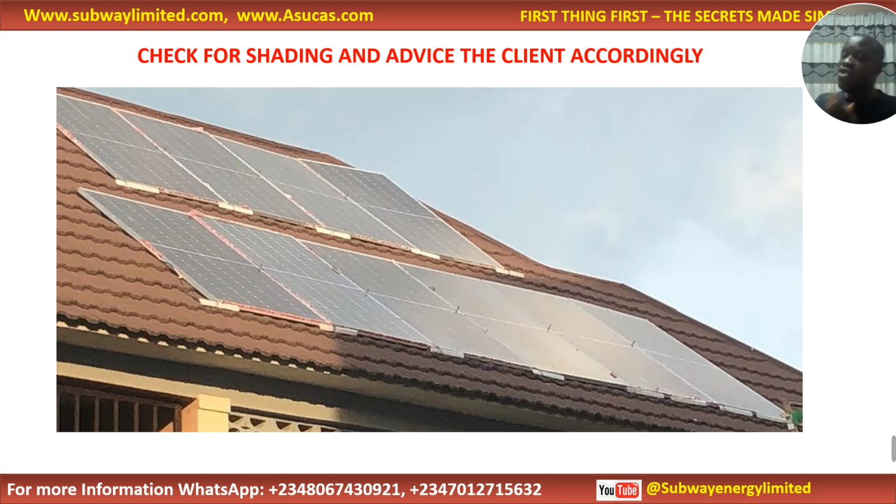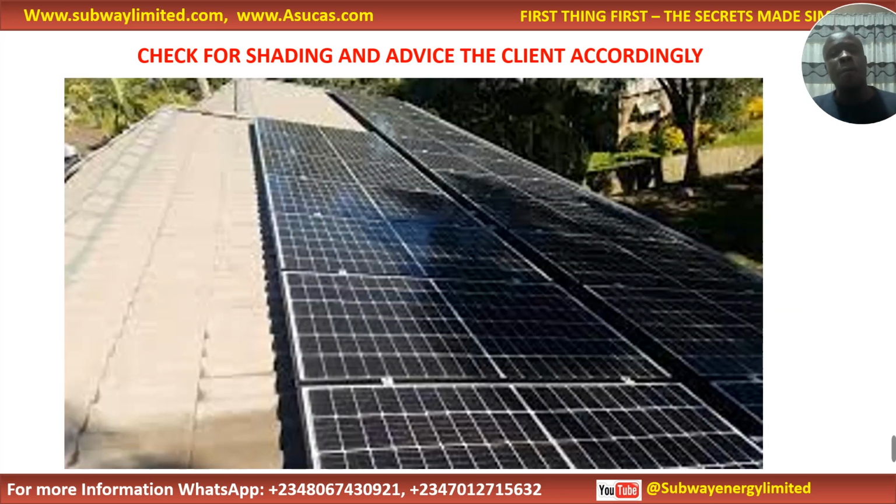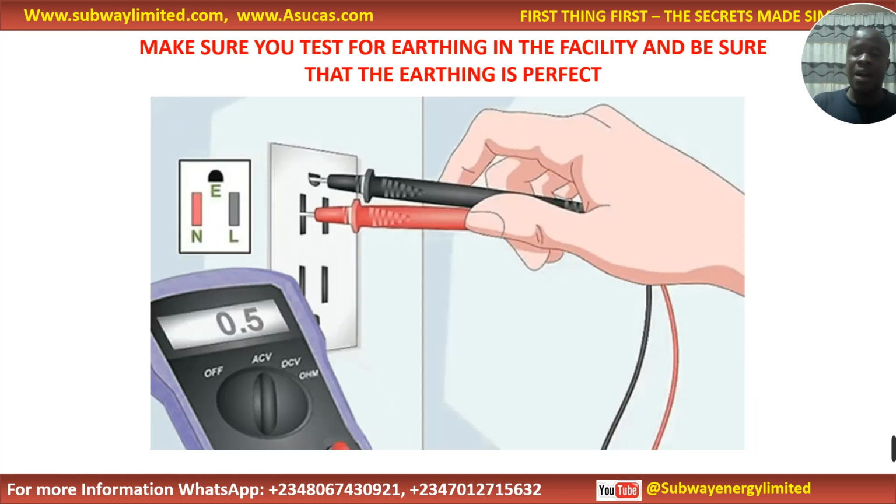So remember, they are using the solar battery. So why waste power? Energy loss is always money loss. So you are throwing money away here. So you don't have to allow any shading come close to where your panel is. This one is the worst. So you cannot carry solar panels and go and mount under shade. This is not acceptable in the solar industry. Check for shading and advise the client accordingly. You can't mount solar panels here until the trees here are cut off.